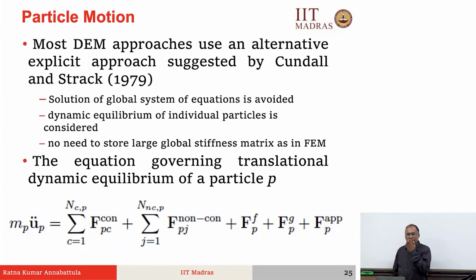Okay? So, this is typically what we would see in systems where the particle size is very small. For example, pharmaceutical powders and additive manufacturing, wherein the particle size is a few microns. Then van der Waals forces of interaction become more and more prominent, because with the very small size of particles, the surface interactions become more important. So, you need to take that into consideration, otherwise you will not get it right. Okay?